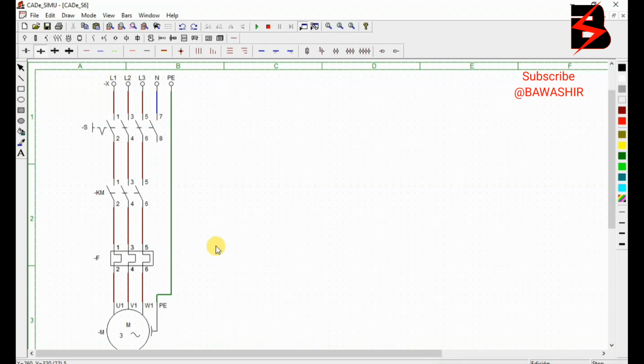So when we try to run this one, actually it can't run, because when I do the simulation, we shall be able only to power the breaker. But now remember, this one is a contactor. How do we power on a contactor? We need some control circuit. It is not mechanically operated, it is electronically operated. There we go. So we can have our control circuit.